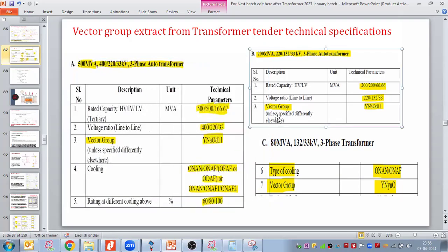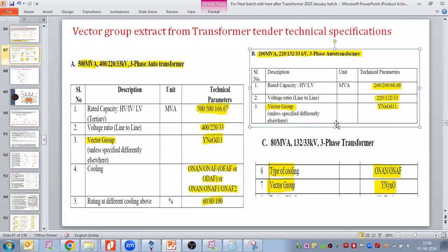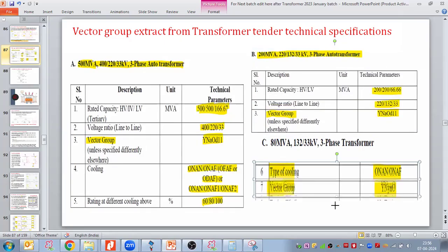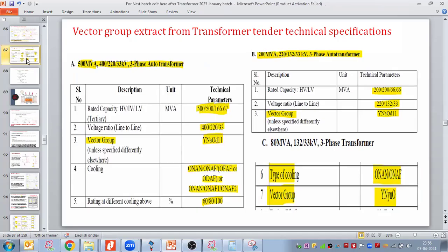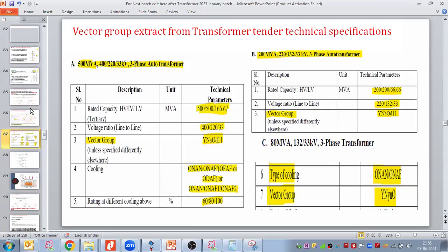That's clear. But in the case of an IDT transformer, inverter duty transformer, when we are representing the percentage impedance, normally I have seen HV to LV mentioned. Sometimes LV1 to LV2 is also represented. Is there any reason for that? Yes, we indicate between each winding what the percentage impedance is. I'll come back to the IDT snapshot.